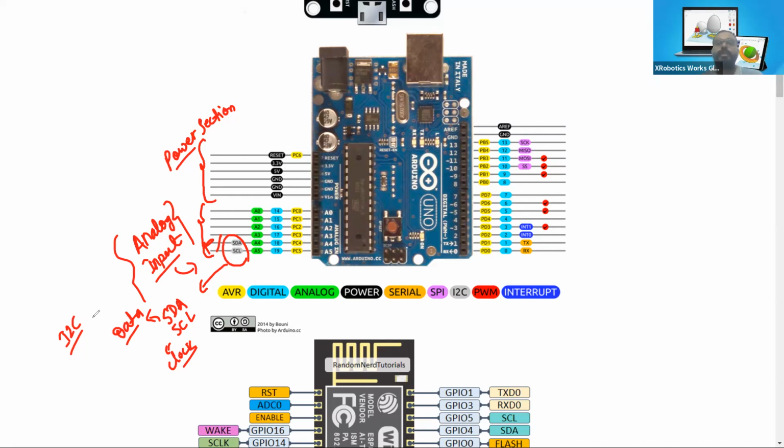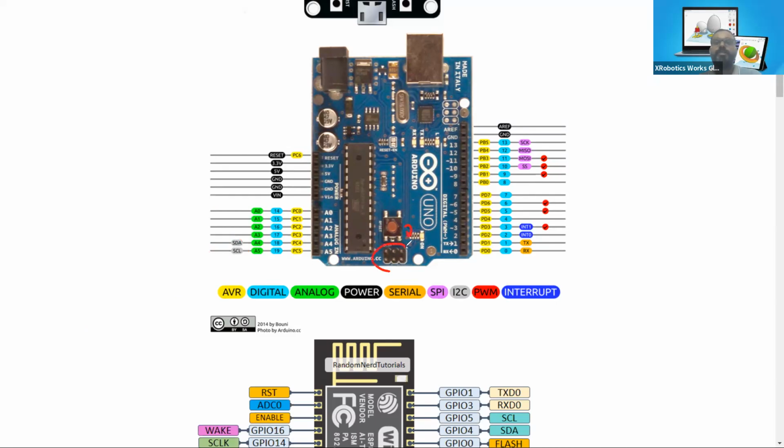And apart from this, similar to other microcontrollers, we have the reset button mounted on the board, and also these pins. Just below the reset pin, we will find 6 pins floating here, right? And 6 of the portions are clearly blank in there. These are known as ICSP pins, which are used as programmers.